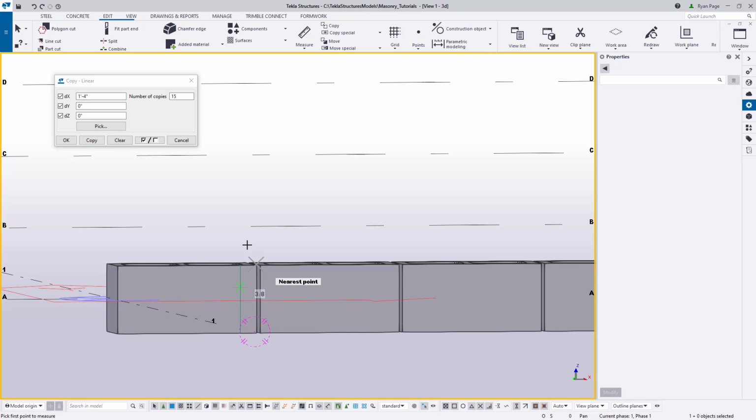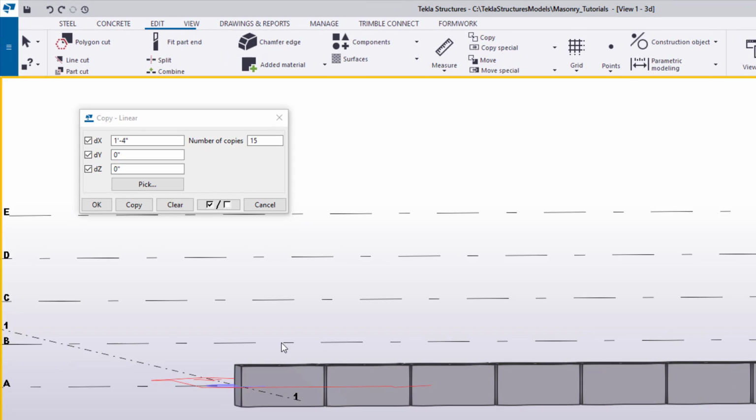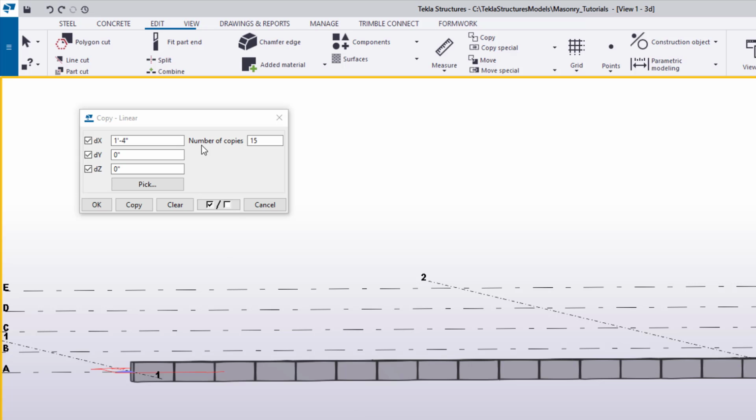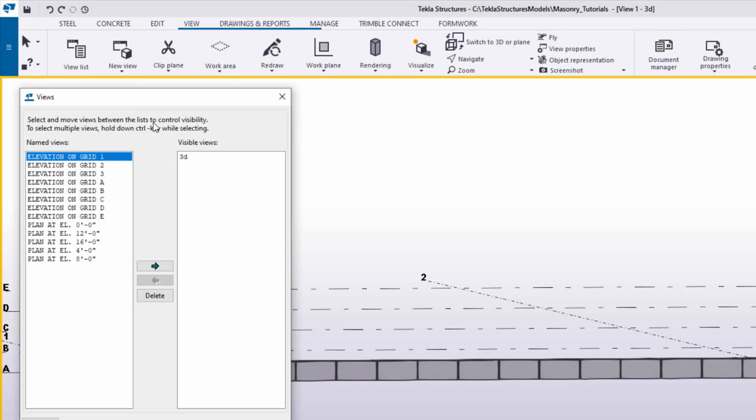When working with walls of any kind, it's important to note that one of the best practices is to actually work in a vertical plane or an elevated view. This makes snapping and just moving around a lot easier, and you stay flush and plane with the actual wall. So to do this, we can go up to the View ribbon and then to the Views list and open up Elevation on View A.